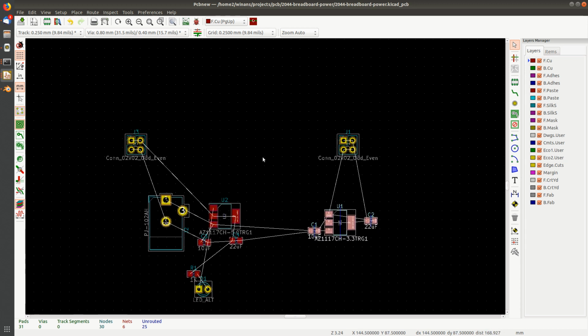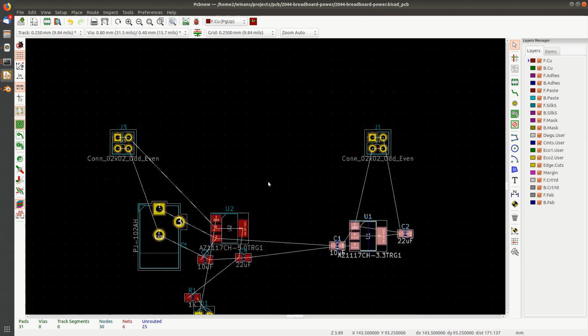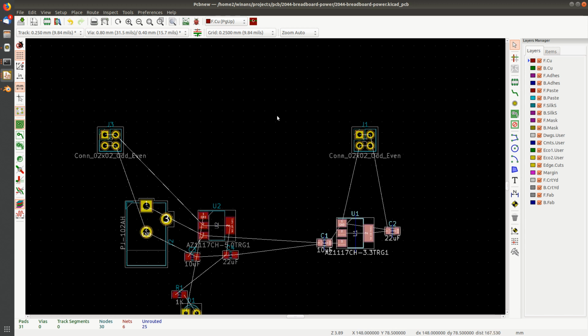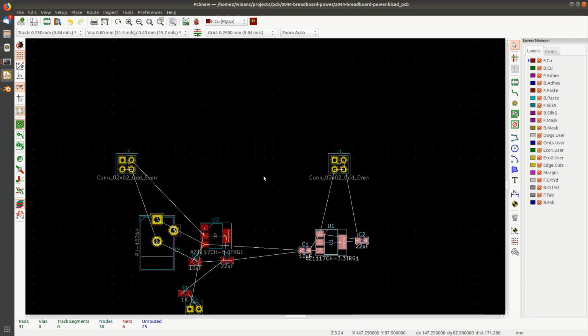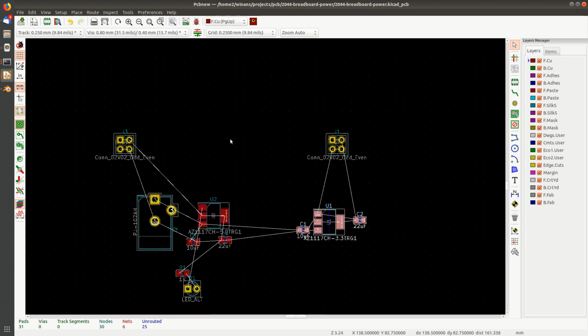Okay, let's talk a little bit about the grid and the fact that these two connectors, these pins, need to be exactly 42 millimeters apart, because, remember in the earlier video, these are supposed to go into a proto board, and with the calipers I measured the center of this pin to the one on the other side at exactly 42 millimeters. So let's start by getting these placed where we ultimately want them, and we'll work around that, because it's the only thing that's certain, right?